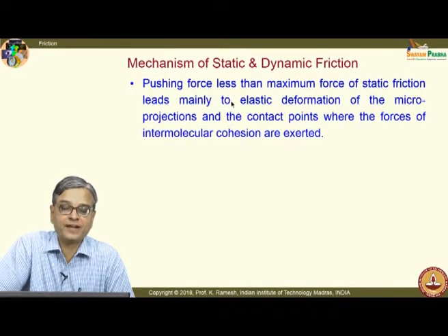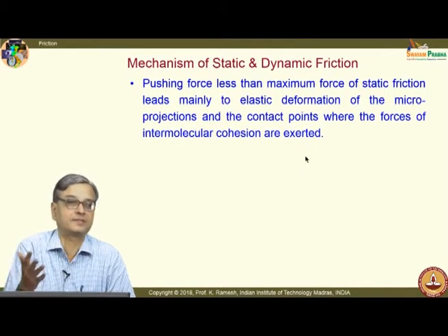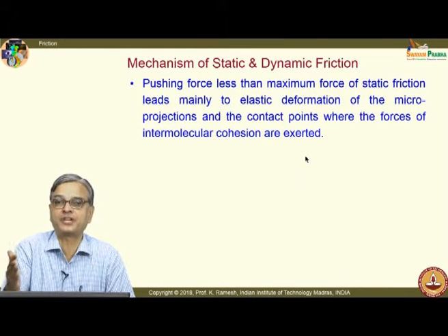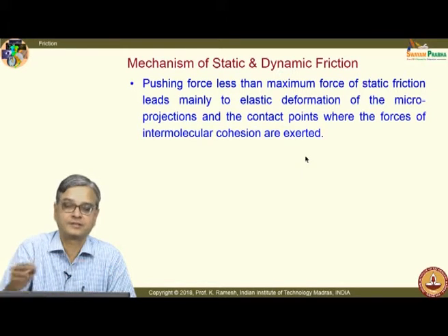What happens when I have the pushing force less than the maximum force of static friction? It leads mainly to elastic deformation of the microprojections and the contact points where the forces of intermolecular cohesion are exerted. That means it is reversible. I have only elastic deformation. When the force is released, it comes back to its original position.